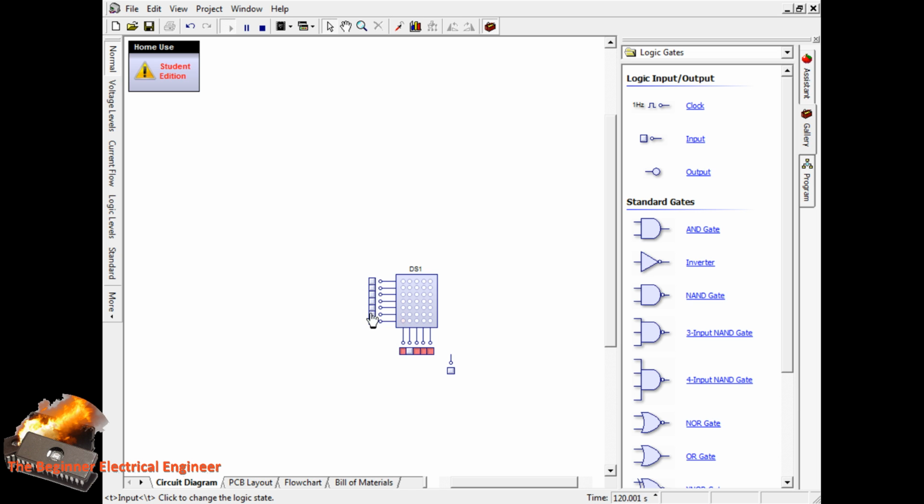Then you turn on the next row, and then do the LEDs that you need on that row, and then the next row, or next column, next column, next column, and then at the other end you do the rest of the ones that you need again, in order to make that N shape, but they just do it really fast so that our eyes can't see it.